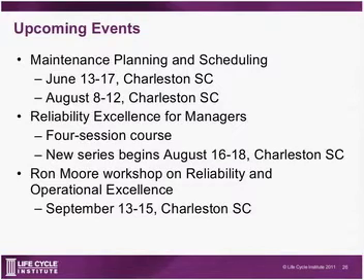It is also possible to measure OEE from line A to line B, but the danger there, as David alluded to, is that you end up not comparing apples to apples. So awareness and education is an important part if we're comparing production line A, which is a continuous production line, to production line B, which is a batch production line. Obviously, we're going to have more downtime due to changeover losses and things like that, so it's not a good practice to measure from line A to line B. Good question. Any other questions out there?